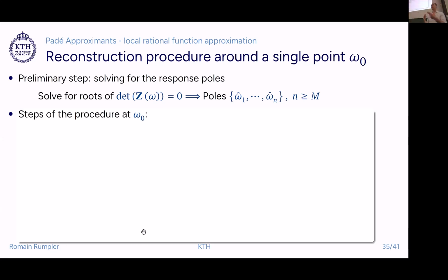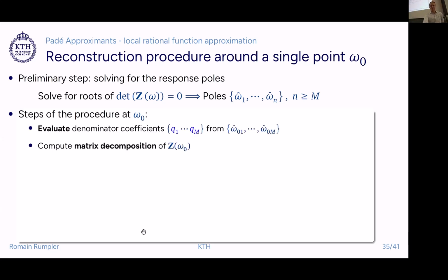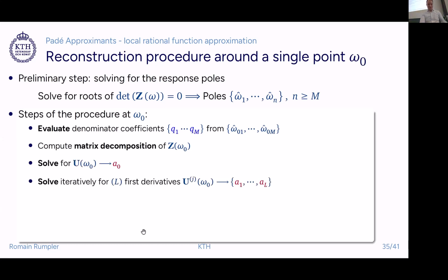Very nice, because the poles in our case, we said we equated them to eigenfrequencies. If we have the eigenfrequencies, we choose a set of them. All the eigenfrequencies that are included define the range that you can at best reach for a converged solution. And then you have an expansion of the numerator that tells you how well you will be converged in this range. So the procedure goes like this.